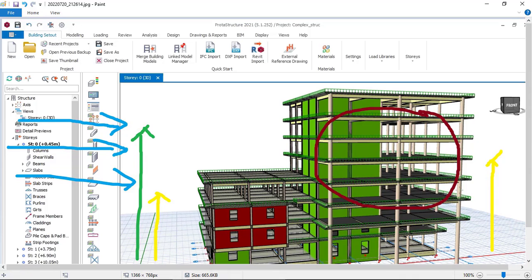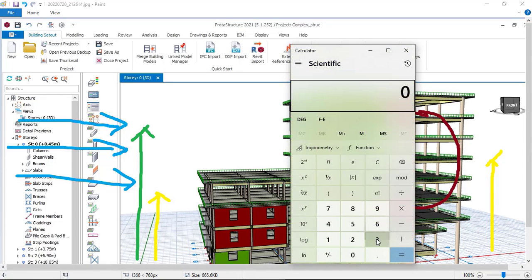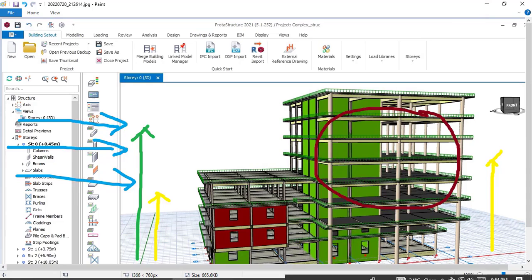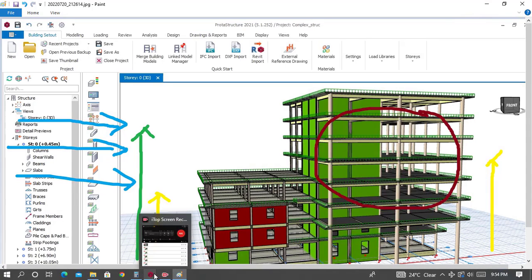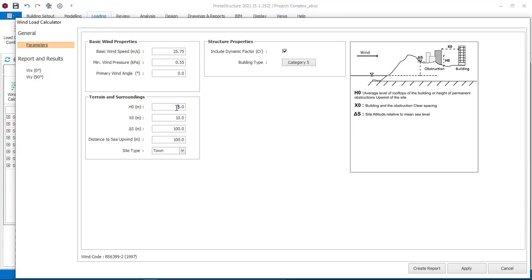So with these features, we have a 5-story building here, a 3-story building here, and tall trees up to the height of 5 to 6 stories. If we check the height of a 5-story building, let me say the story height is 3.3 meters, so times 5 or 6, that gives us 18 meters high. So we used a height of 15 meters as the height of this obstruction found before our building. So we use 15 meters here.